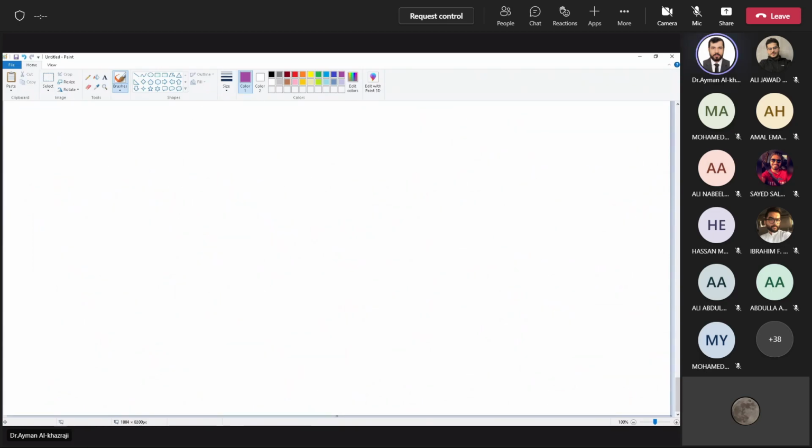So this is normally what we have. The remaining things are simple, direct, straightforward, like what we have taken. PID controller, simple. There is a question where you find PCR and KCR, and you have the table: 0.6 KCR is KP, and then KI and KD.